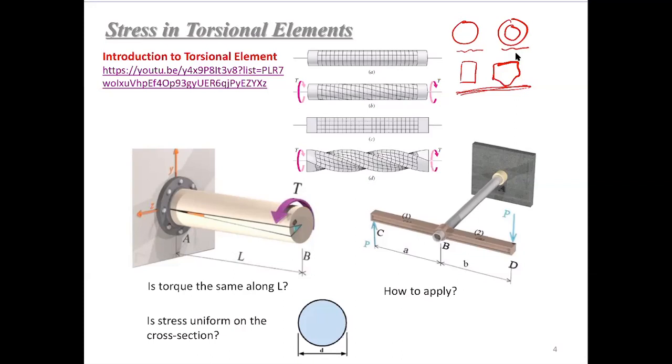In these kinds of elements, when they are subjected to torques, you will generate shear stresses and an angle of twist, as I mentioned. Let's look at the first simple example as shown here. It's a simple shaft, one end fixed at point A, and we're adding a torque to the other end B, and the overall length AB equals L. At end A, we fix this shaft, meaning that at this point, no deformation is allowed. This plane at point A will be fixed there. No deformation is allowed to it.